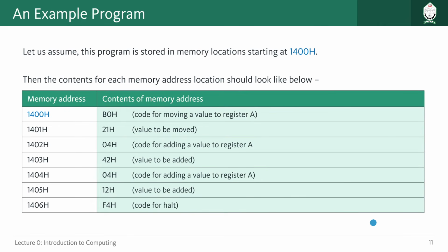Now before we run this program using a CPU, first of all we have to store that data in any kind of memory, right? That can be ROM. So in the ROM, let's say we are trying to store this data, and for ROM each of the rows will have some address, right? Memory locations. So we have to start from any memory location to store the data. So let us say the starting memory location we have selected is 1400H. It is arbitrarily taken for this case, you can assume.